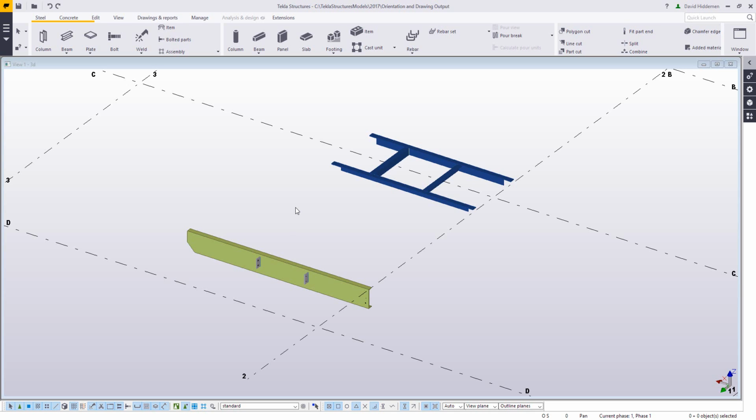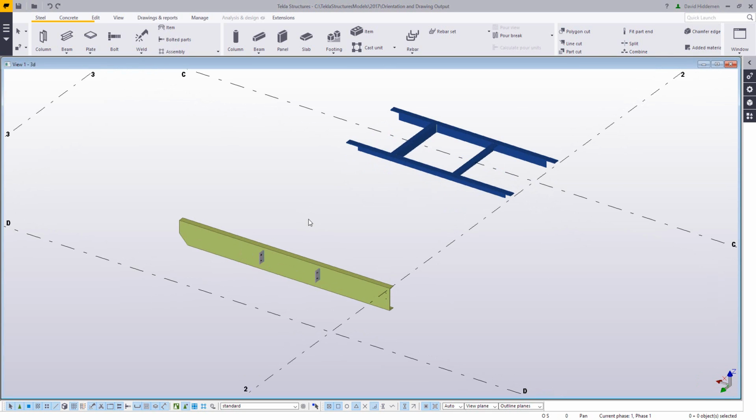And today I want to show you how you can use fixed drawing main view settings to better control the orientation of your parts and assemblies in your shop drawings. So first, to explain what I mean by that, a lot of people will make their channel drawings and they don't realize that we have out-of-the-box settings to make sure that it's always showing the channel toes away or from back of channel. So what they get is something like this.